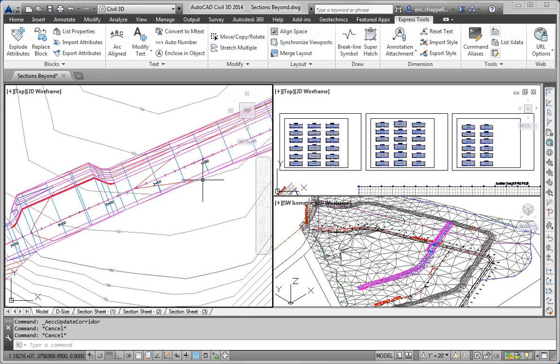Using the section editor, we removed the ditch from that part of the corridor. So we went in and changed a few settings at a few stations to make a small change. Now if we wanted to remove the ditch from hundreds and hundreds of feet along the left side of the corridor, we would have to handle that possibly a different way.